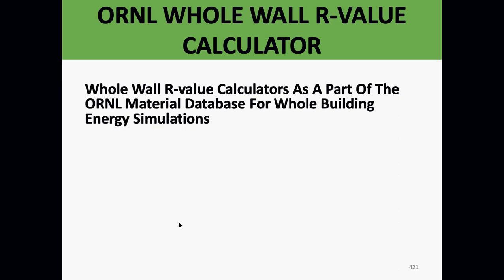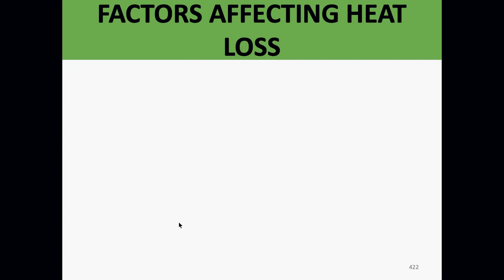They have the ORNL, which is a government agency, and it has an R value calculator that I'll be posting the link for, for whole building energy simulations. They've moved it from where we thought it was going to be, so I've had to go find a new link, and I'll post that into the course. Don't worry much about that, but I do want you to know it's there. It allows you to actually build the wall and select different insulations for R values. It's a neat thing, and it gives you some dollars lost and dollars gained.